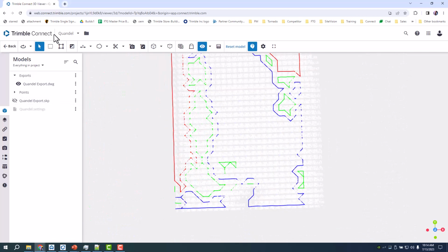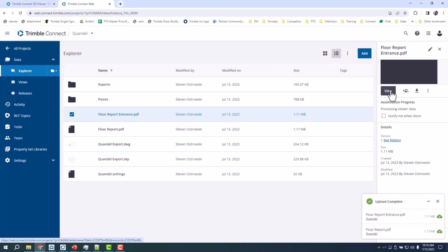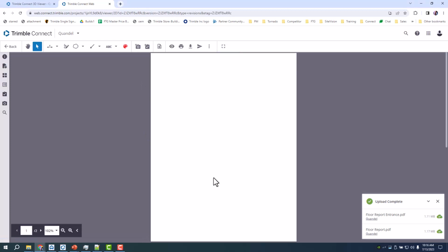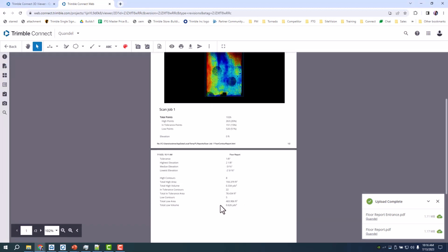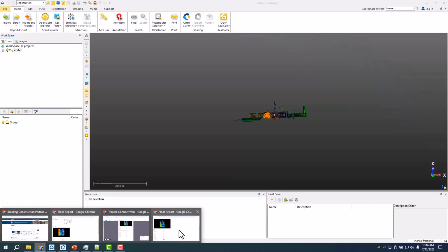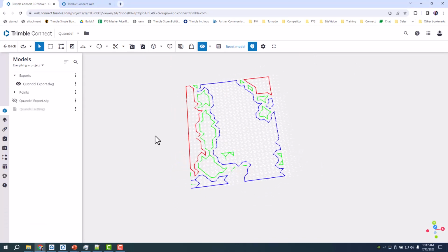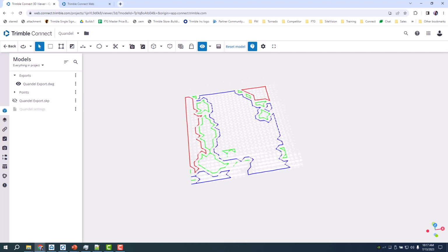And then if I want to, I can open up that report that we created. And so here is that report, high and low area, that I can send. And this DWG that was also created could be given to the client as well. So good estimate, good quality, and clear. So that's how to do a quick contour creation and surface analysis for estimating if you need to raise the floor or anything like that, even stockpiling, reporting very accurately. Thanks.